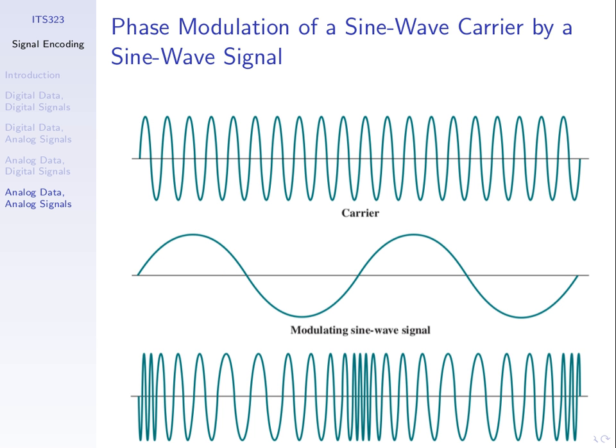Does the frequency of the carrier always have to be 105? The frequency of the carrier is what your transmission system is designed to use. For example, with FM radio, one company gets a license to use frequency 105.5 megahertz as their carrier signal. The way those licenses are allocated, another company can get a license at a different frequency, and they need to be separated by enough such that they don't interfere with each other. Because remember, we don't transmit at that exact frequency, we transmit at a range of frequencies centered on 105.5. Our signal has a range of frequency components, and similarly this signal has a range of frequency components centered about 106.1 megahertz. The center frequency is 105.5, but there are components on either side.